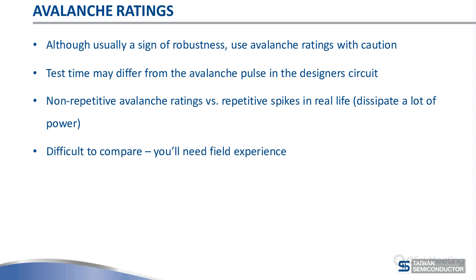But if your design does use avalanche, be aware that most avalanche pulses are single events, and you may have repetitive events, so you have a bigger power dissipation. And here it is really difficult to compare apples to apples. You're really going to have to use it in the field with tens of thousands of pieces to see if you have a significant change in your field failure rate, yes or no. So avalanche ratings are critical and tricky to compare. That is for higher voltage rectifiers.